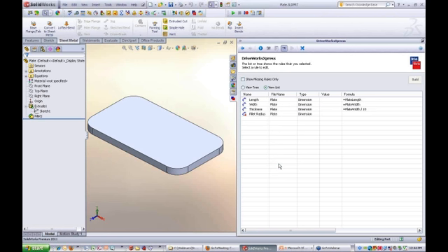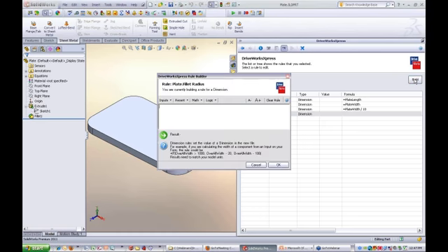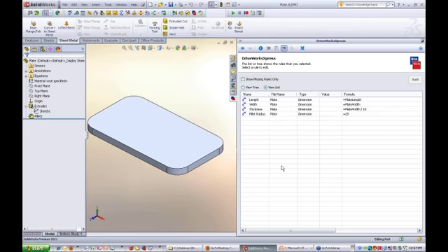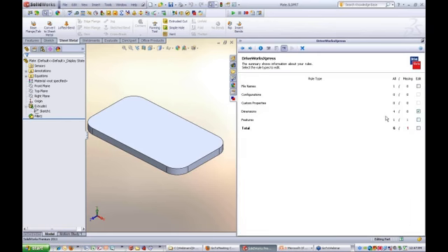You don't have to have a formula, however. You can do it other ways. So for example, the fillet radius, I'm not going to control that. I just want to set that. So I can simply build that and let's just make it 20 and just give it a fixed number. So all our dimensions are now controlled in one way or another. So we go back. It shows us there are no missing rules for dimensions. So I can untick that one.